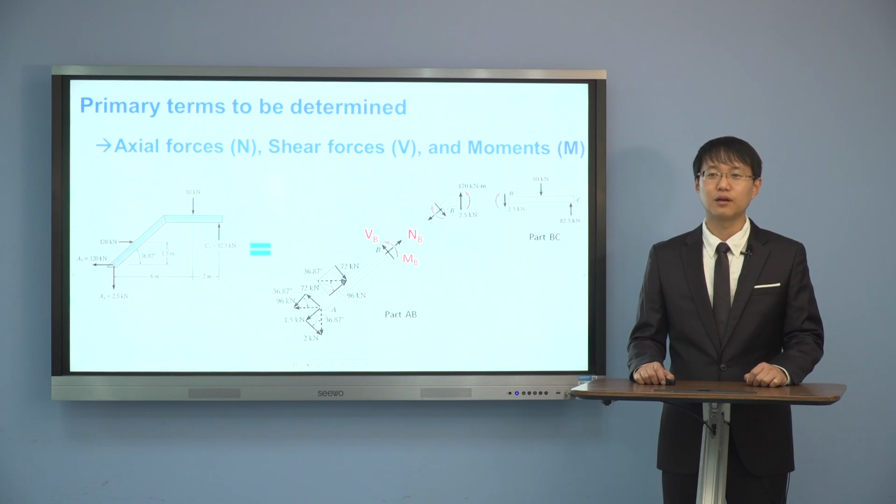And these internal loadings can be determined by equation of equilibrium, and also these internal loadings can be found at other points of the frame structure, and we collect those internal loading data, and based on this data we can construct shear force diagram and bending moment diagram.